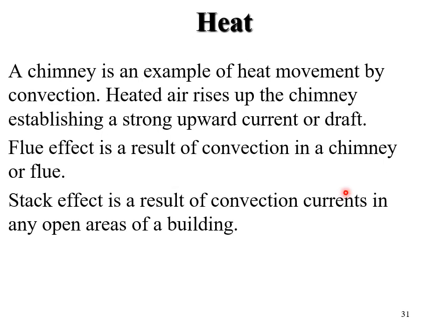A chimney is a great example of this. As you heat the air with a fire, for example, that air wants to rise, and then that will establish a strong upward current or draft. So the flue effect is a result of the convection that happens in a chimney or in a flue. Stack effect is a result of convection currents happening in any open area of a building.